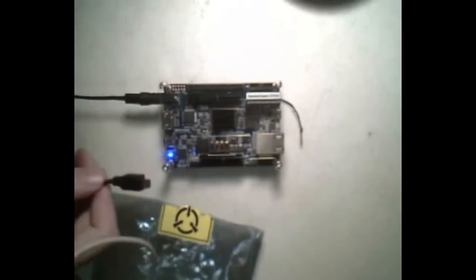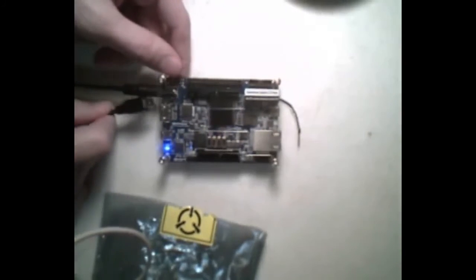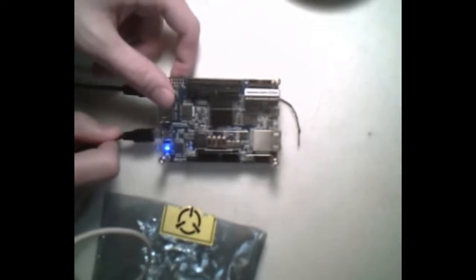And that's really what I'm going off of, and I'm just trying to show you that the steps are going to be the same every single time you want to put a design on your board. Bring in your USB cable and plug it into the J13 if you want to look at the number on the board. It's the one that's the USB and it's next to the power cable on this side. Plug that in.